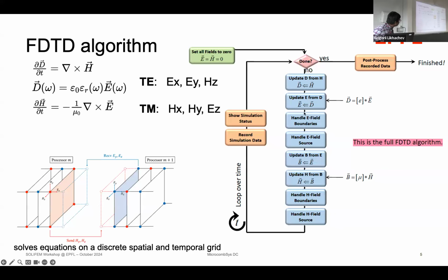You can see my cursor here. So you would update the D vector from the H vector that you injected from the first equation, and then you update your electric field from D is just epsilon naught E plus P. And then again, you would go back and inject the electric field vector that you got from this equation, and then solve for the magnetic fields, and then you just continue this in a loop, and that is going to be propagated all the time.